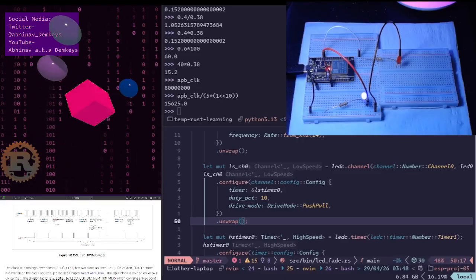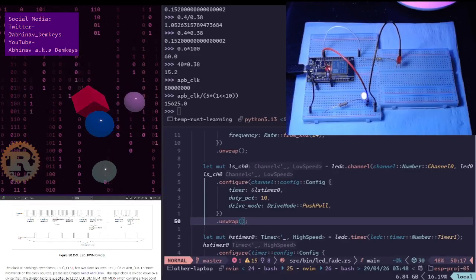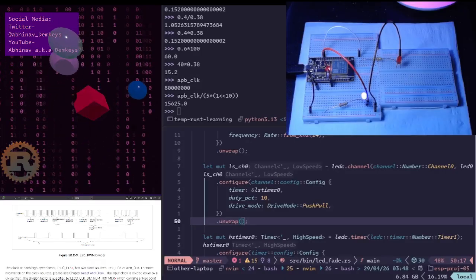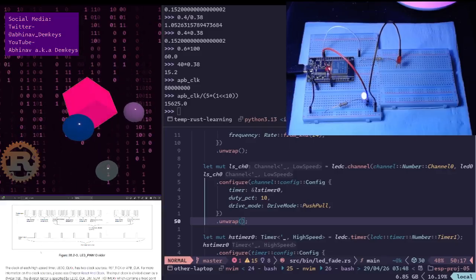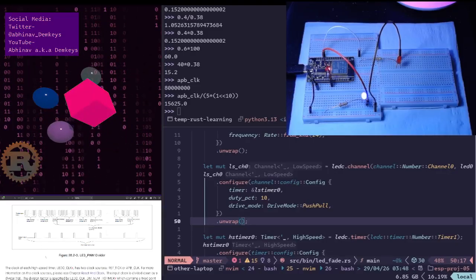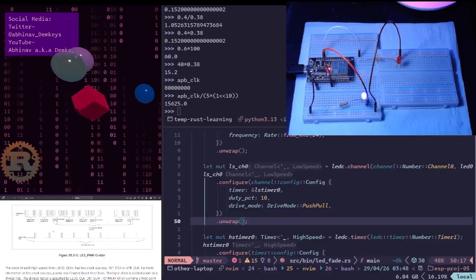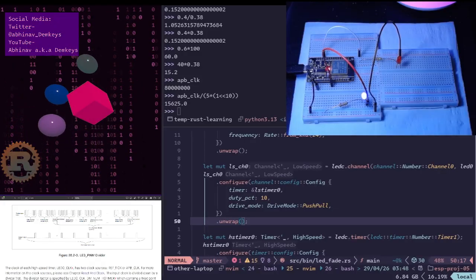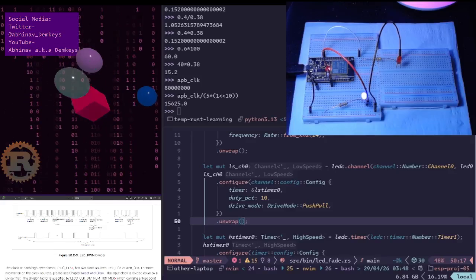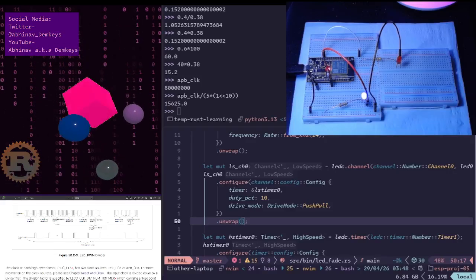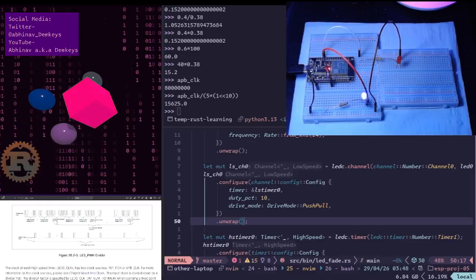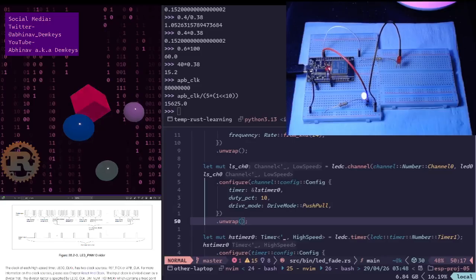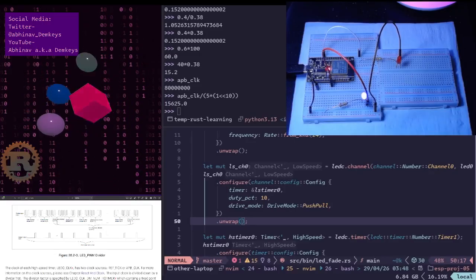I'm assuming this is the 80 megahertz signal, and the clock divider makes it so every set number of ticks, it counts one tick, and that one tick is going to be used in the counter in our PWM hardware. So we have a counter that basically just counts the number of ticks, and those ticks are what we use to determine that we have finished one cycle.